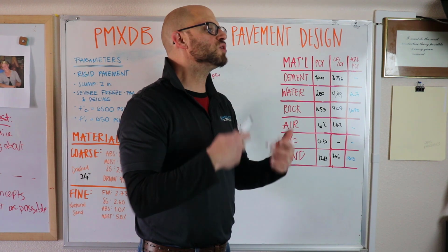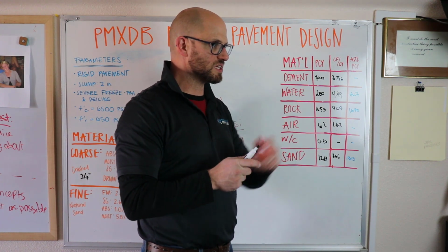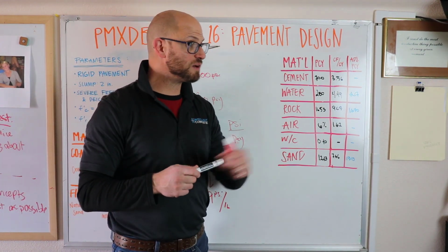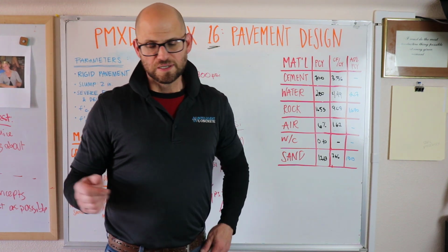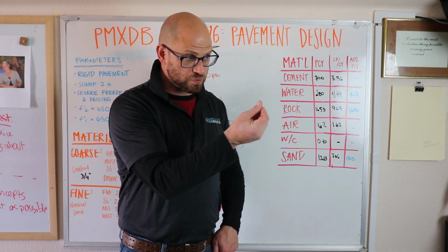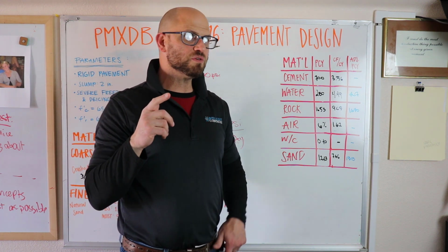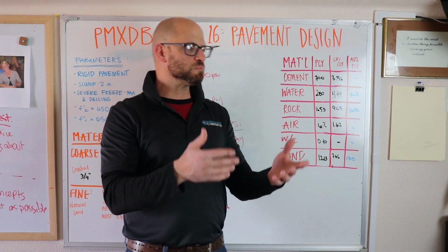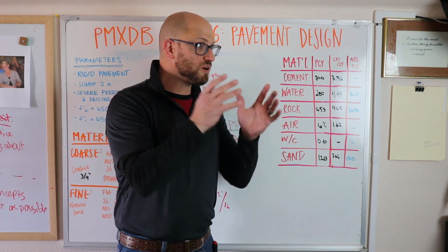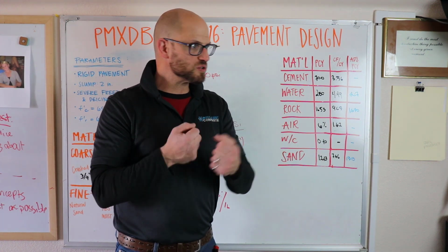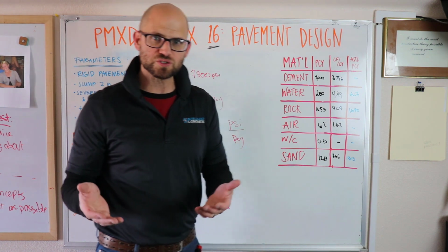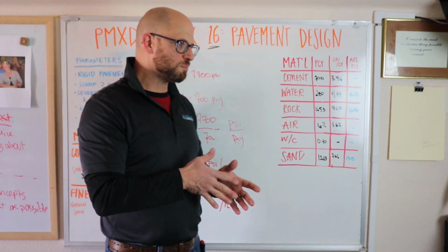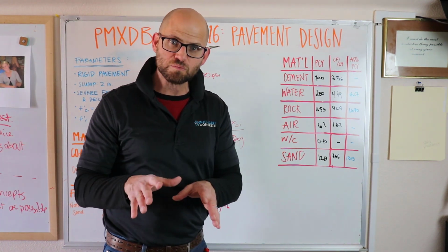Now, Haley, why don't we want to increase our cementitious content more than we need to? Because it's expensive and it's bad for the environment. Right, it's expensive. How is it expensive? It's the most expensive material in concrete. It is the most expensive material in concrete with cost, right. But if you throw more water at rock or sand, nothing really bad happens to it. If you throw more water at cement, you're going to create a very soupy mix, soupier than what you originally started with. So the cement can be the most expensive component because it is one of the more difficult components to deal with in our concrete. So bear that in mind too.